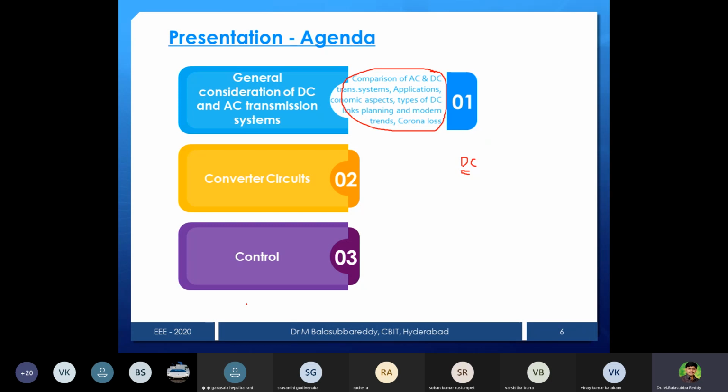That is one of the topics anyhow. The smoothing reactor, in the sense that whatever we are converting, we pass through the reactor so that it nullifies some of the higher order harmonics. They are of very low magnitude, so an inductor is sufficient to smooth them out. That reactor and all have been working for even 76 years. So reliability is higher comparatively.